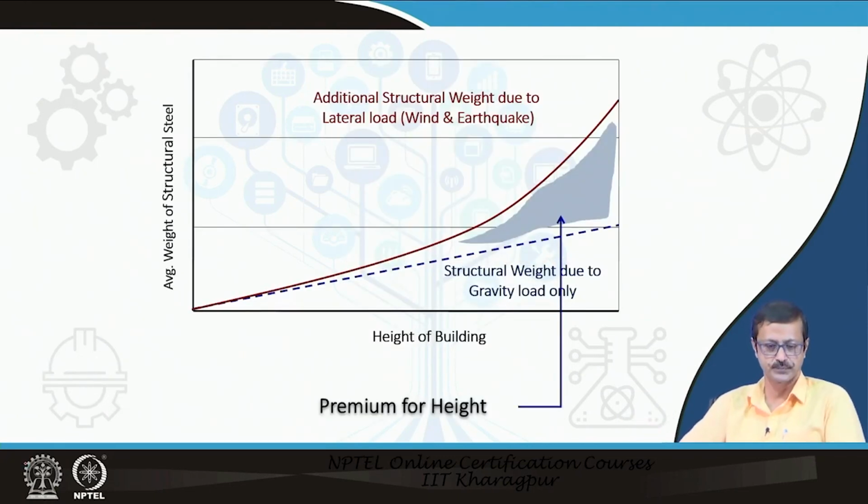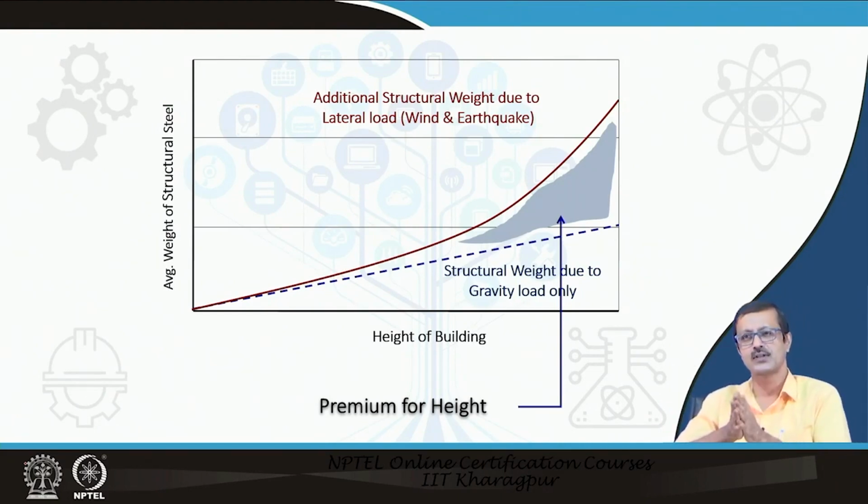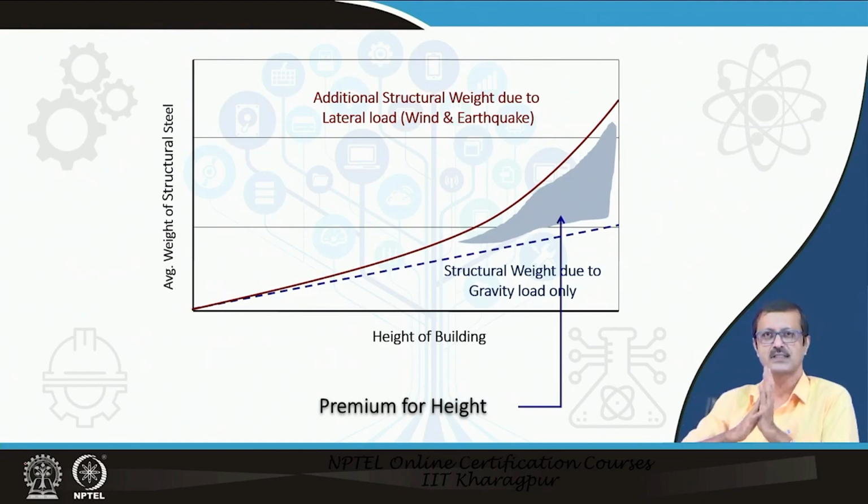Khan developed the tubular and this exterior kind of system with some of his projects. So, what he told is that as and when you go high, if you want to go 50 storied, 60 storied, 80 storied building, probably much more, then there are two loads, as we have always been saying from the last fourth week lecture or so. It is the gravity load, which is the dead load and the live load, and there is a load called the lateral load, which is basically wind and sometimes earthquake.